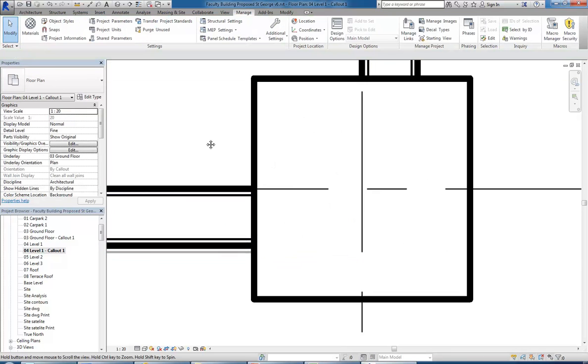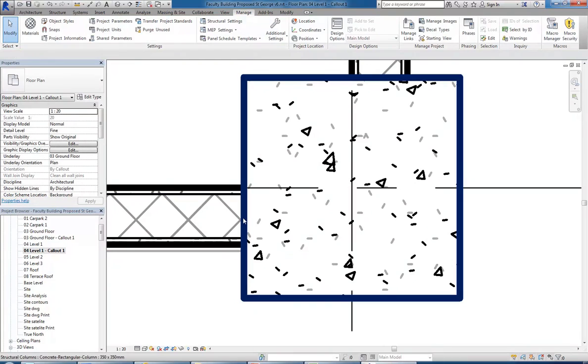But that's not the main issue. The other issue is that we've got a heavy line there, and that shouldn't be heavy. I know they tell you at first that everything being cut in your floor plans should have a heavy line on the outside, but that's not entirely the right way to describe it. It's really the envelope, the outside edge of things that are being cut, the exposed edge, that should be heavy. So here, that should be a light line. Do you know the trick to make that light?